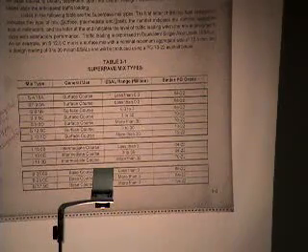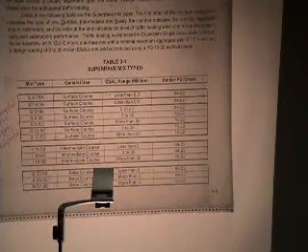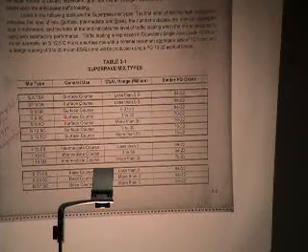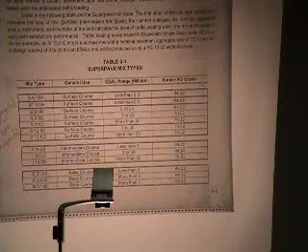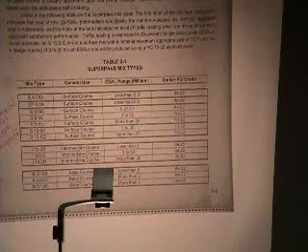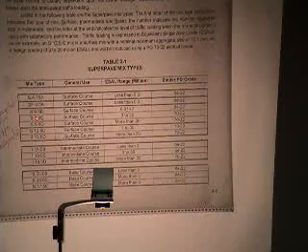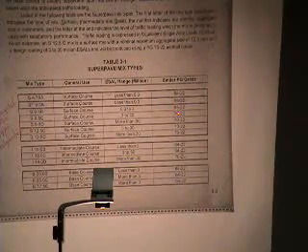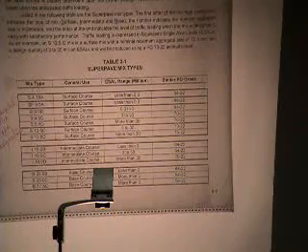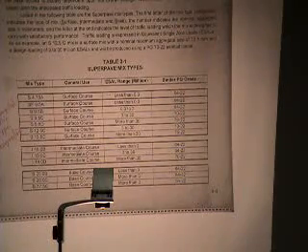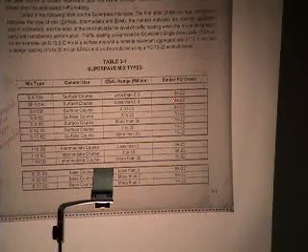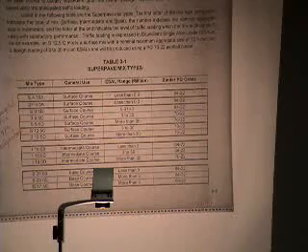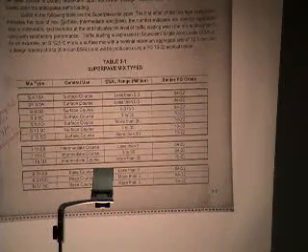And because of that lower traffic, we don't adjust that based on the load. When we do get to the C and D level, where we have heavier traffic, then we want to consider that. So if you'll note here on the 9.5C and 12.5C mixes, we bump, the term they usually bump, where you increase the temperature grade, we bumped up from a 64 to a 70. That's a stiffer asphalt to give you more rut resistance.